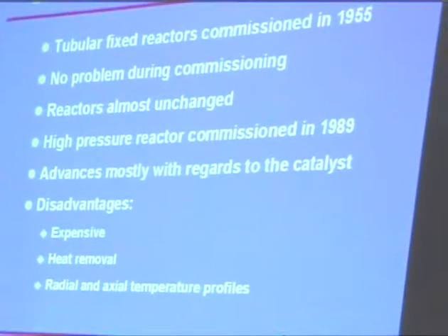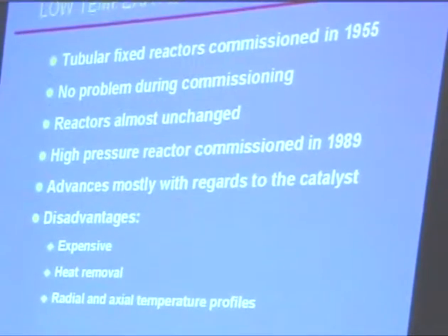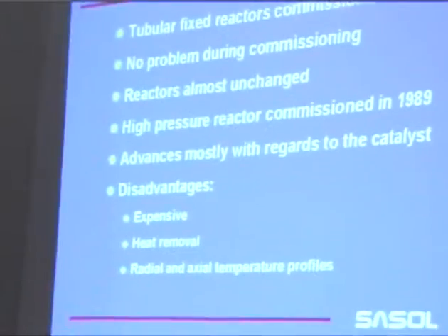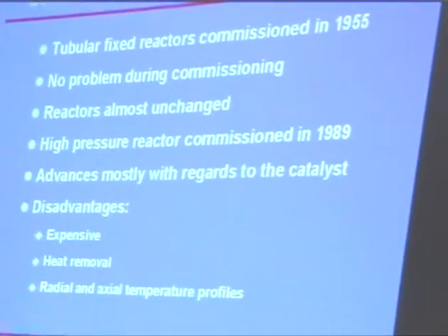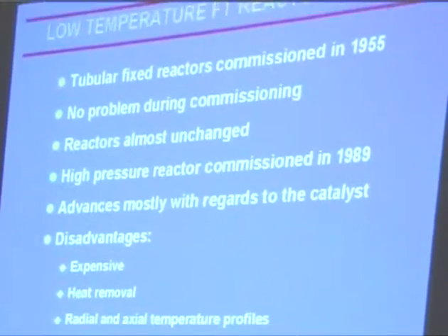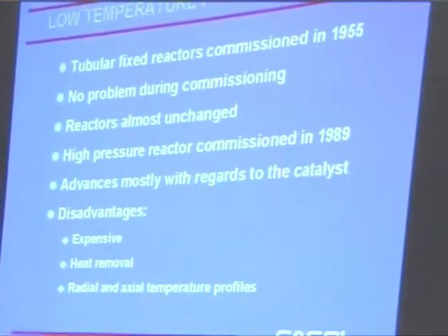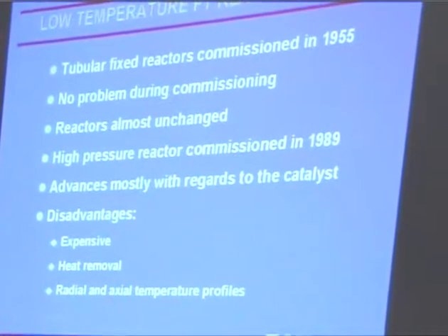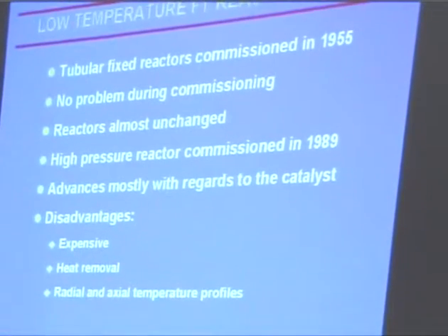We have replaced the tubes in two of these reactors, so 2 of them are still the original reactors. They still have the original recycle blower working there as well. What we have done is to optimize the operating conditions and also to optimize the catalyst composition. The catalyst is now much more active. We have a very high wax selectivity from those reactors. We have increased the throughput through the reactors.